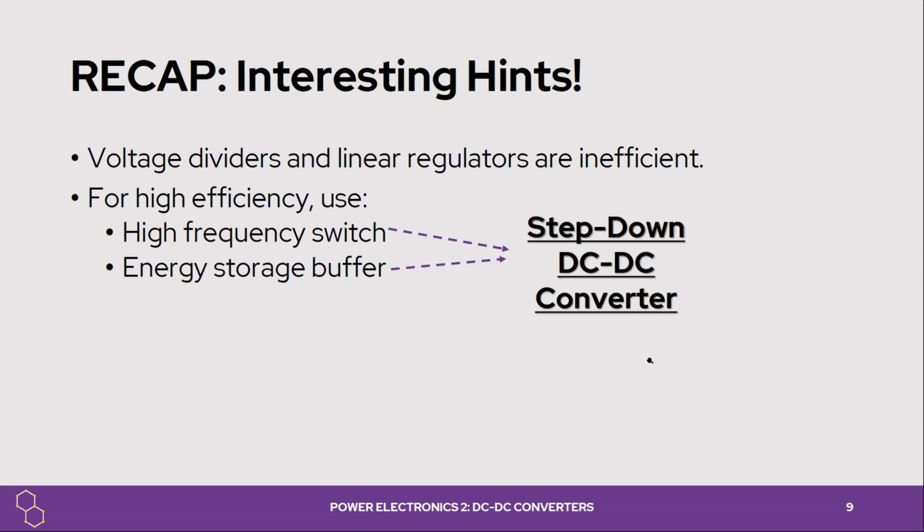As you know, from the Fourier series, we define the DC voltage as the frequency 0, and that's what we're trying to get. But using power electronics, it's hard to get only the 0 frequency with no harmonics. You can get some frequencies, but the point is to minimize the other frequencies and to maximize the DC voltage frequency, which is the 0, which is the average value of the curve.